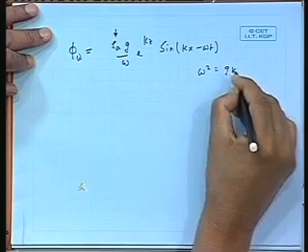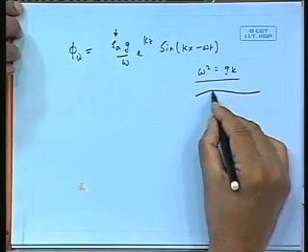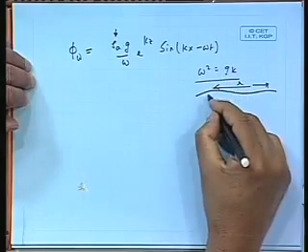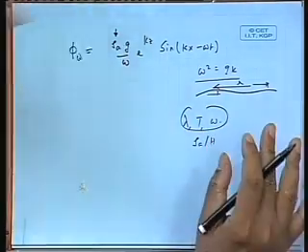Another thing that is important is that this dispersion relation, omega square equal to g k, tells me the wavelength. What is wavelength? It is a parameter of the wave along the x axis. It relates wavelength with period and frequency, but has no relation with respect to height. So, height or amplitude always appears as an independent parameter. You can always have a 10-second wave which will always be 150 meter long, but that wave can have a height of 1 meter or 2 meter or 3 meter or 4 meter. Height has no relation with length. It is only length and omega that are connected, but xi a or h, the height parameters, are independent.